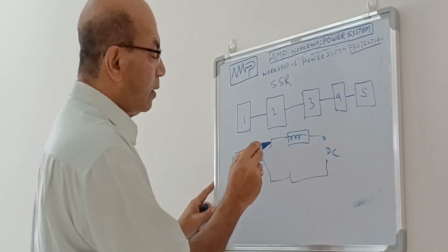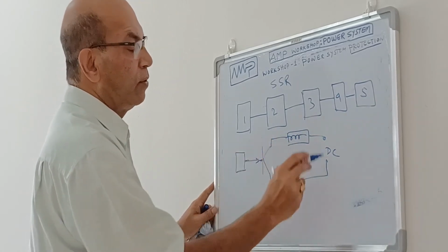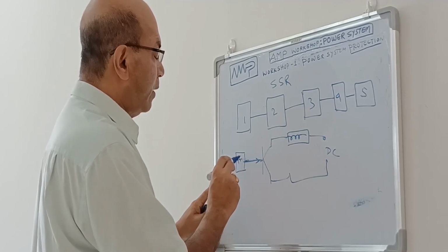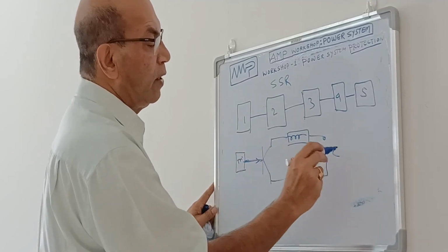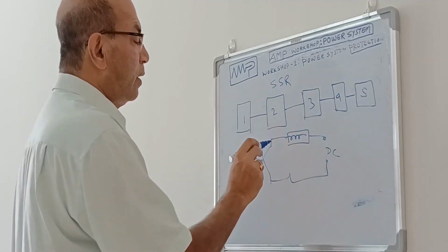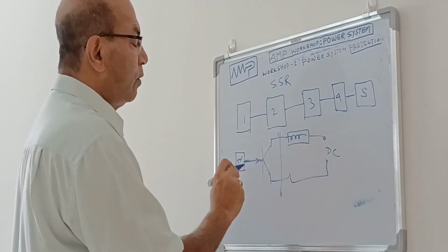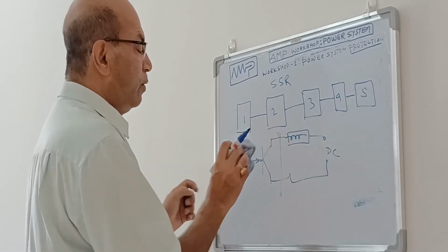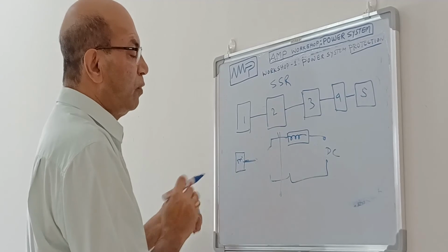Normally when this transistor is not conducting, there is no current through this. The moment the signal from the trigger circuit comes from here, it immediately starts conducting and current flows to this load. This up to this part is the relay part. So the relay is conducting. In the case of an AC circuit, we cannot use this FET or MOSFET. We have to use the SCR.